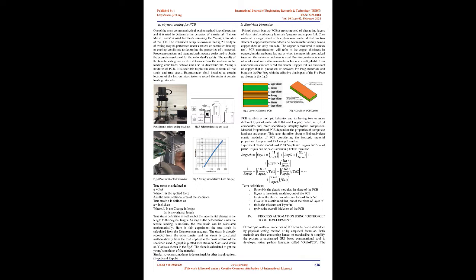Multi-layer board. A multi-layer PCB board, Fig. 1, is used in situations where the density of connections needed is too high to be handled by two layers or where there are other reasons such as accurate control of line impedances or for earth screening. The multi-layer board makes use of more than two PCBs with a thin layer of what is known as prepreg material placed between each layer, thus making a sandwich assembly.